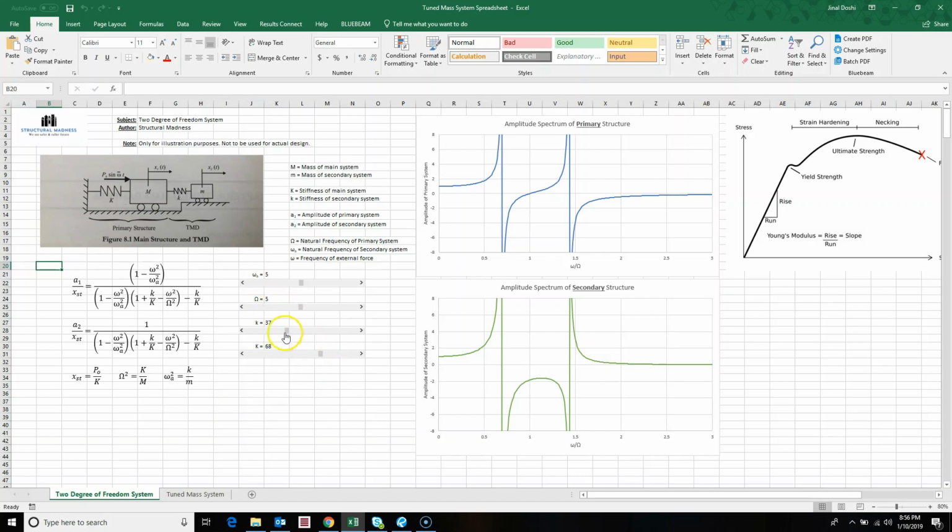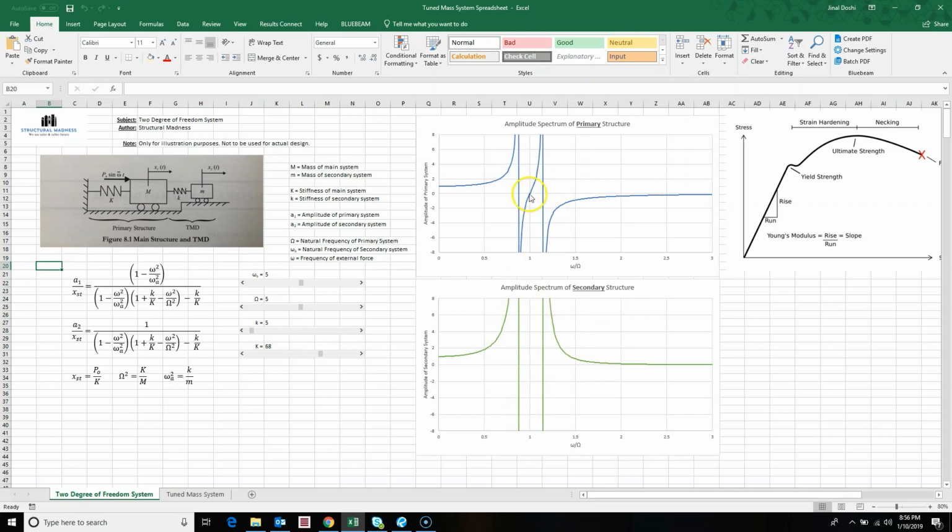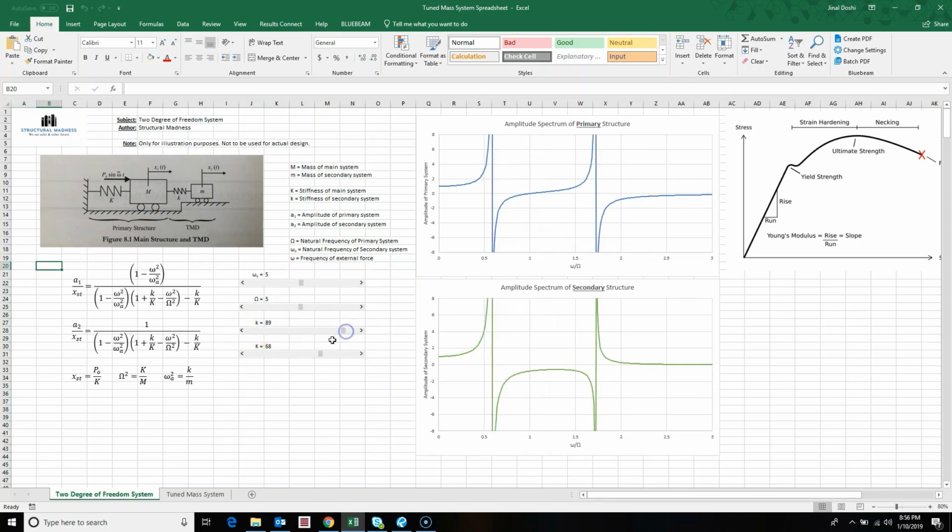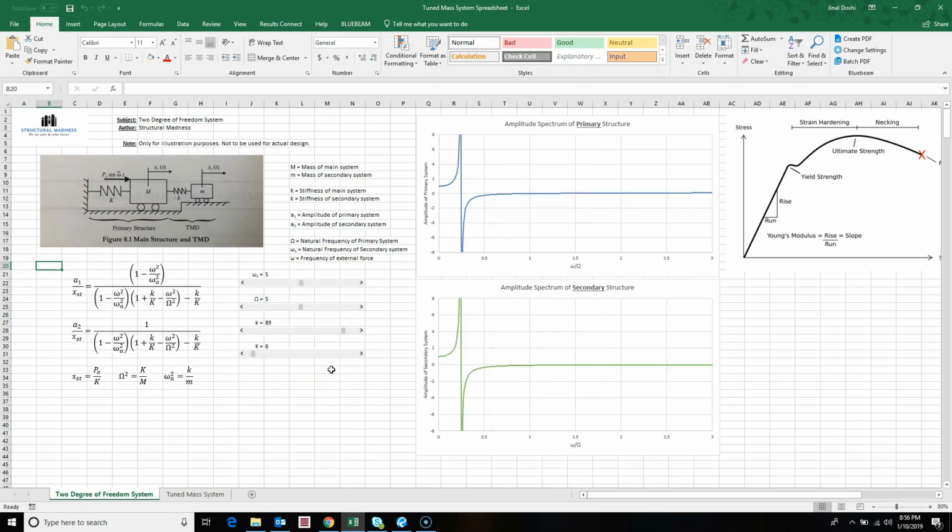Now this, you can play with 4 different parameters, and understand how the stiffness of the damper and the stiffness of the system also affect it. For example, if the damper doesn't have any stiffness, you see this band becomes very narrow, and that's because if the damper doesn't have stiffness, it's not going to get excited so easily, and it's not going to absorb that much load. But let's say if it's exactly opposite, the damper has too much stiffness and the primary structure doesn't, and it's like putting your building on top of like 4 jelly beans or even gummy bears.